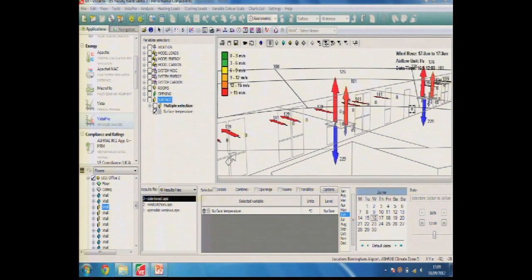And the quadrants that are downwind are in that negative pressure region as a result of the flow separation around the Windcatcher terminal, are therefore doing extract. So we've got a complete supply and extract circulation of air to the room, which gives us real confidence in the way that IES is actually replicating the performance of our systems in reality.